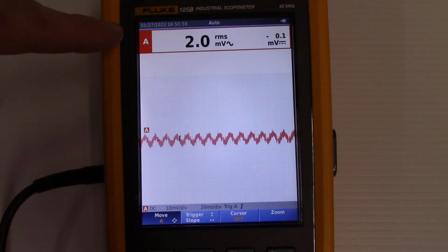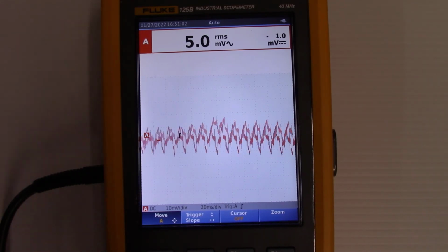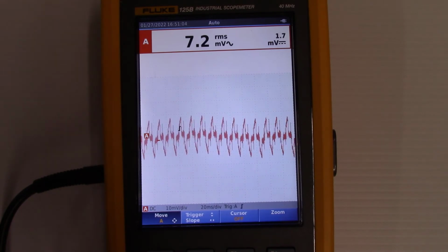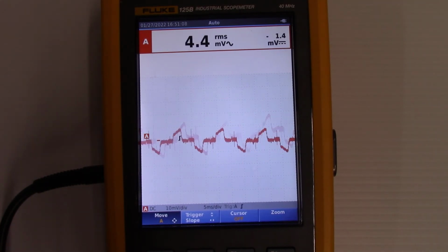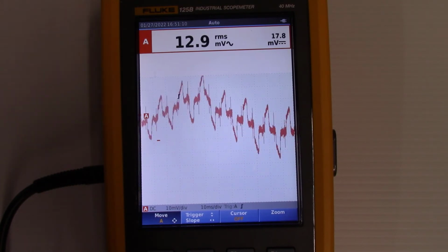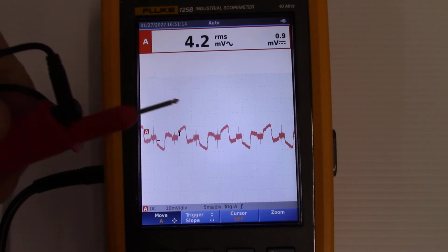You'll notice that we just have channel A active now. We will set channel B active in a couple of minutes. First, you need to go over your probes. It's very important to know your probe polarity. So we have a current probe and then we have our voltage probe.